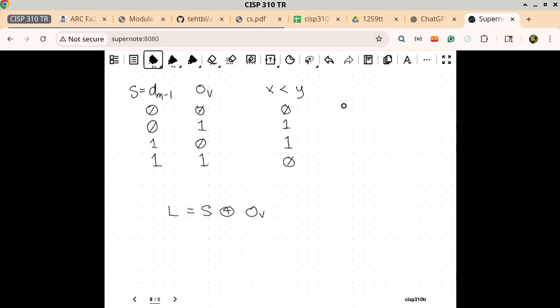Okay, so we'll focus on the subtraction. And we don't really care about the entire subtraction other than what happens to the most significant bits. In other words, we only focus on x subscript m minus 1, y subscript m minus 1, and then d subscript m minus 1. Those are the only three that we need to take a look at. Why? Because we can tell by the sign alone whether there's an overflow situation or not. Okay, so we'll put this on another truth table on the following page. Are we ready to move on? Because I have to flip a page.